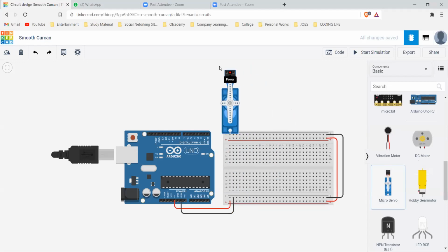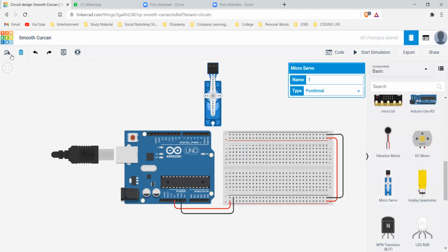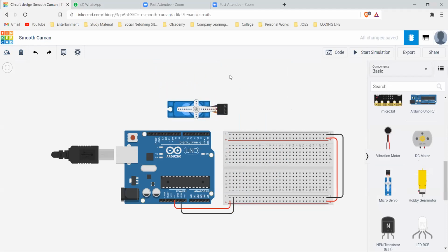Okay. So let's just place our servo. So let's just consider even we do not know any kinds of connections that we need to do for a servo. It's new to us. So how do you know which is what? You just hover over it, we'll get this is the ground. So this should go in the negative. Okay. So it went into the negative.